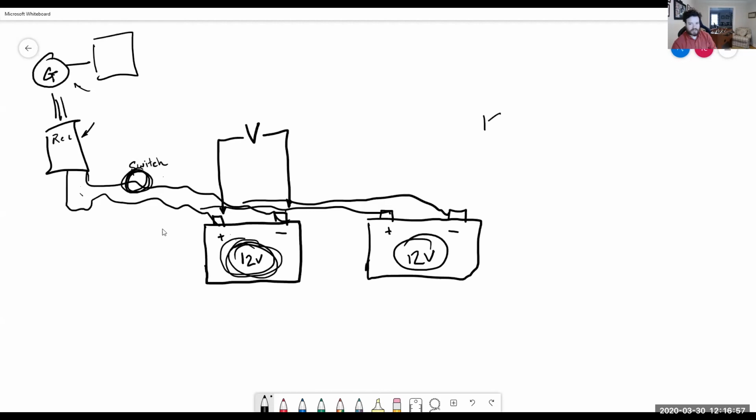Most of the time you'll just get something like 12.04 or 12.13. Really, it's one of those things where you're going to see a battery stay fine, and then it'll be a slow death. When you're stuck on a boat for weeks, you'll see these things: all of a sudden it'll be 12.00, and then 12.0, and then as you start to go down, you see that dreaded 11.